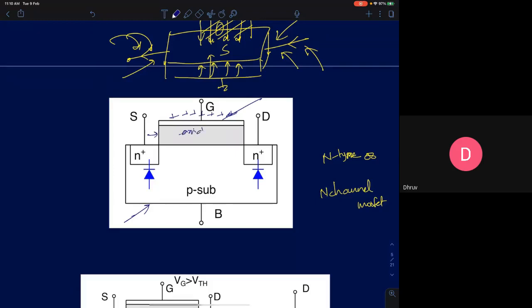This oxide, I told you, was introduced to resolve the problem of surface effects. For the field to penetrate the surface, you needed that. You take silicon, oxidize it, and you get silicon dioxide, which is a good insulator. I gave you an example: insulator, semiconductor, and conductor. What is the fundamental difference between all the three? What distinguishes them?